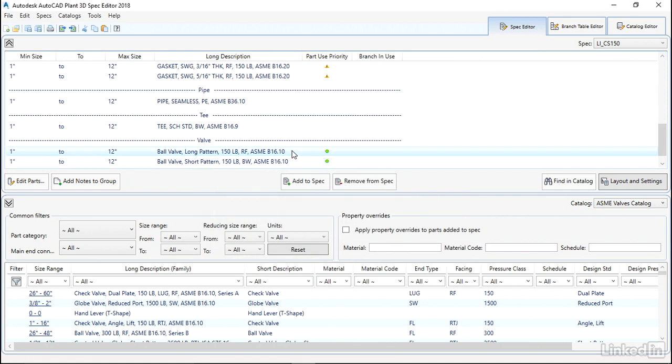So now when these parts are being used, the designers will be prompted for a list, and all it is is a selection list. And again, we're actually telling it to put the one that we're most likely to choose at the top of the list. So this is part priorities. As tedious a job as this is, it will make life easier for the designers over the course of the project. It's not necessary to set up a part priority, but it's always good to know that the feature's available and what the advantages are going to be when you actually use it.